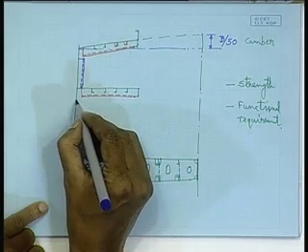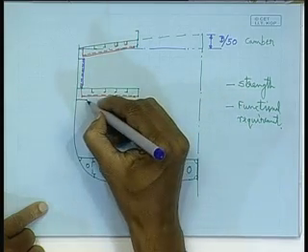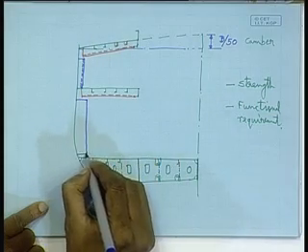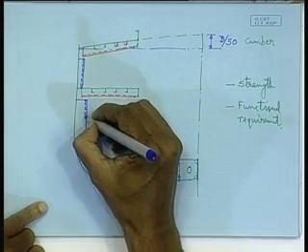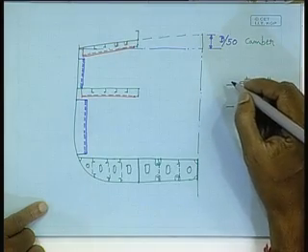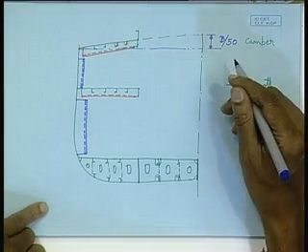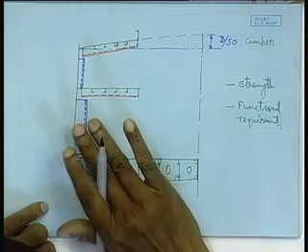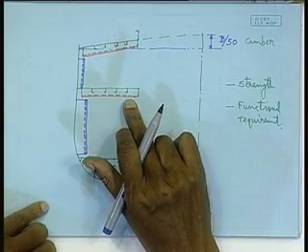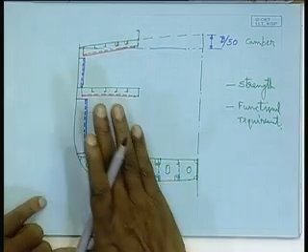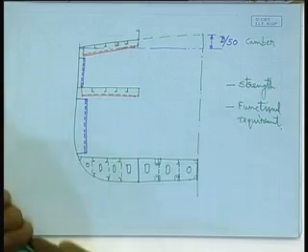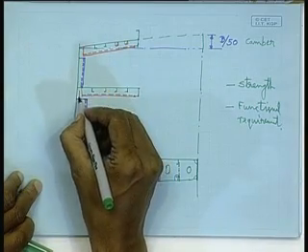And the transverse stiffeners would look something like this. That means the side shells are transversely framed. They are in the transverse plane, isn't it? Like that of the deck transverse we have drawn in red. They are in that plane, right? And they will obviously be connected to each other by a bracketing arrangement.